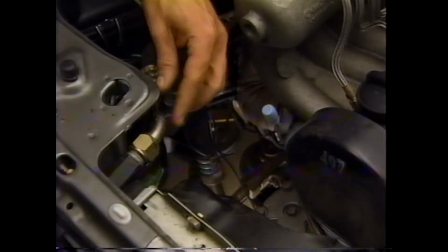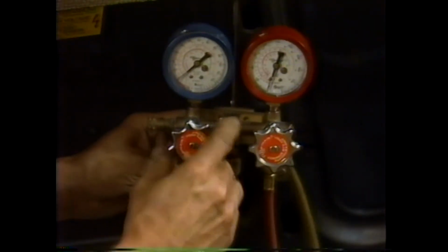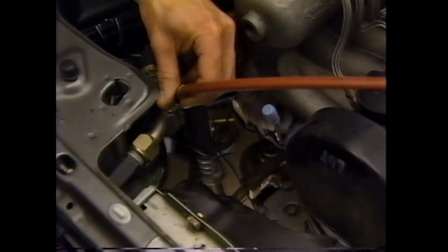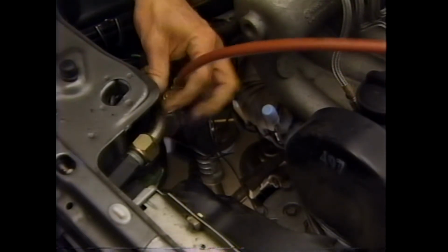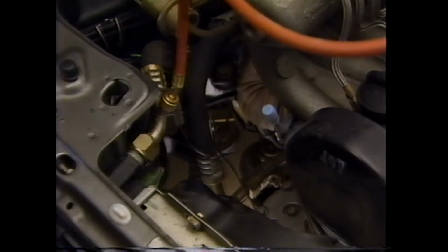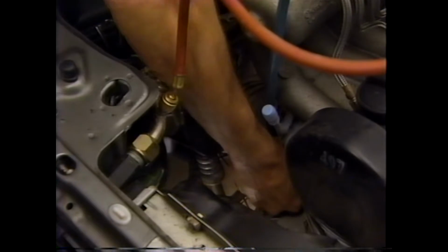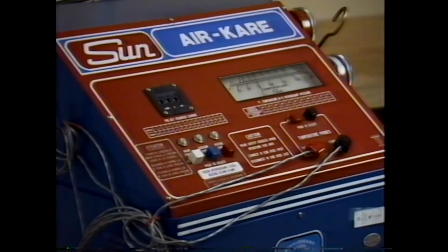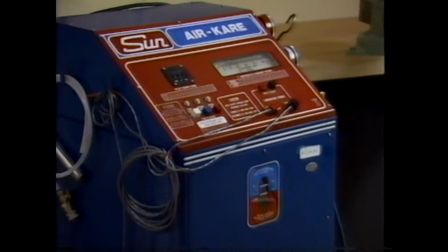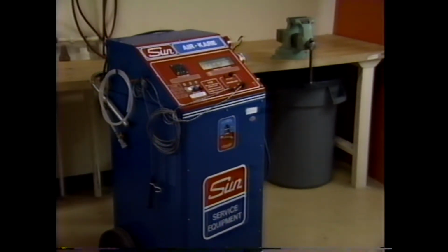With the engine off, remove the caps from the service ports. Be sure both valves are closed on the gauge set. Then connect the high side gauge to the discharge fitting. That's the one between the compressor and the condenser. Then connect the low side gauge to the suction fitting. That's the one between the evaporator and the compressor. If you're using a charging station to conduct your system performance checks, follow the manufacturer's instructions closely.